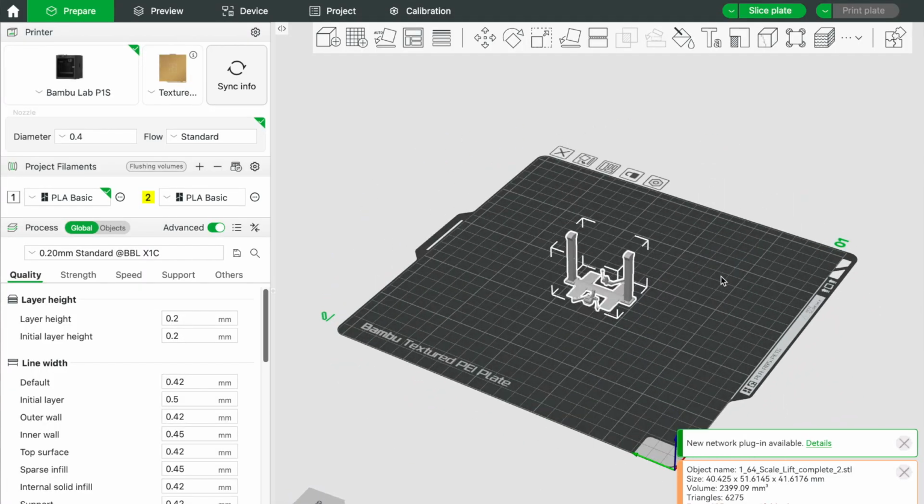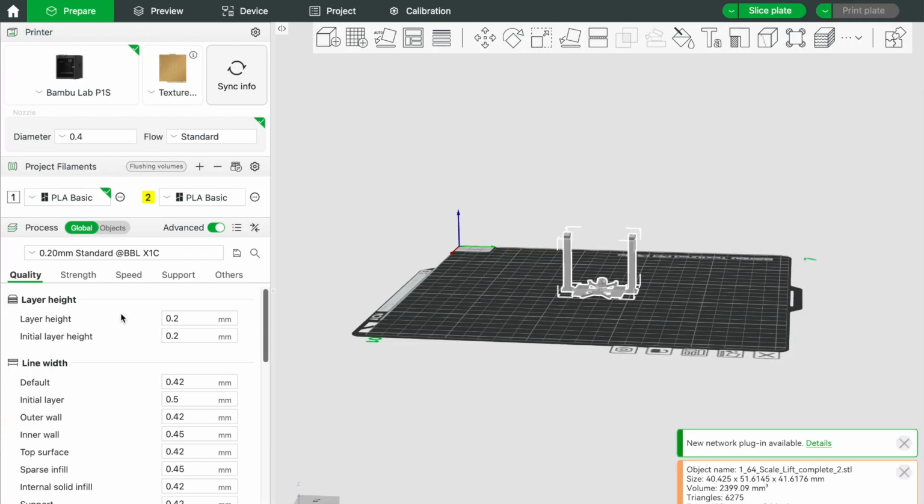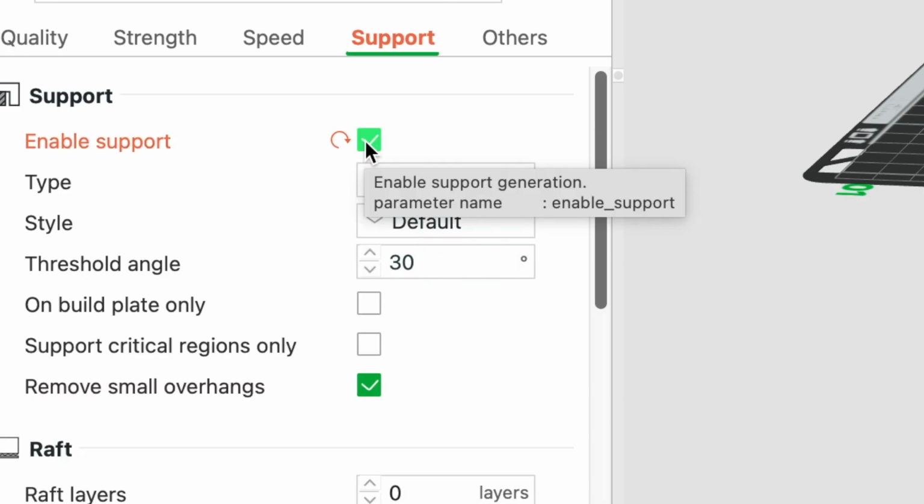You can download its own app, and it'll slice it for you, and you can do whatever you need to do. So basically, you just get your design and you put it onto the slicer. You figure out, do you need support? Because a 3D printer can't just make a piece that's hovering up in the air. So you need to 3D print a support up to it, which it'll automatically generate, and then you can make your 3D print. Once you figure everything out, you need a way to get it from the slicer onto your